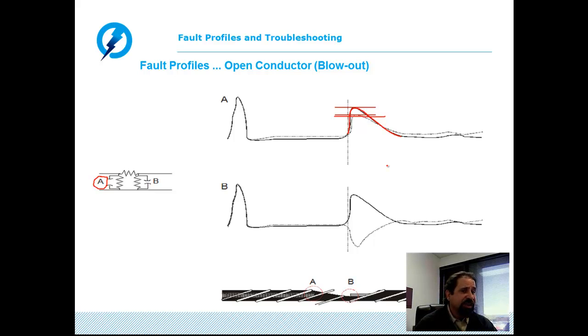Again, in a situation like this, an option would be to move the equipment to the load side of the circuit and shoot back. On the load side of the circuit, if the gap is more reasonable and we're able to get stronger discharges, what we would see on the low voltage radar is initially the image for the open circuit.